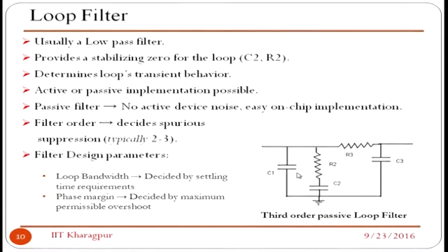Look at the transfer function of this: you introduce some poles in it so that stability is satisfied. The loop bandwidth might be sacrificed because of the introduction of the pole, but that will improve the stability of the loop. You can make second order filters, but it is always desirable to go for a third order filter, introducing another extra pole that will give you stability.